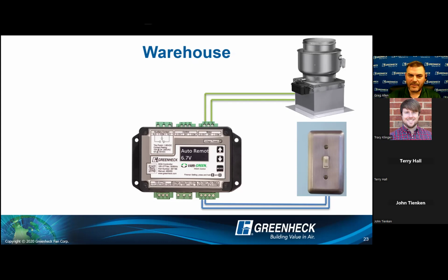In this scenario, my translator that I brought up earlier, if you're speaking 2 different languages, light switch, open, close. If it's powered, power, no power, right? It's sending Greek and my fan is looking for French. The HOA in this scenario becomes the translator between those 2 devices. I'm accepting my binary and I'm outputting a modulating.